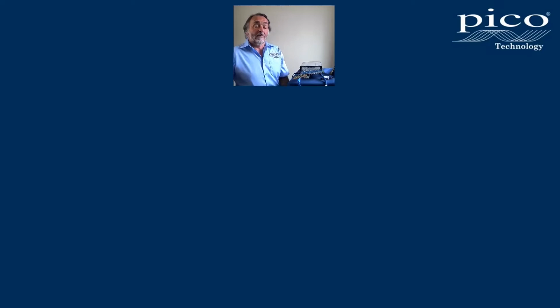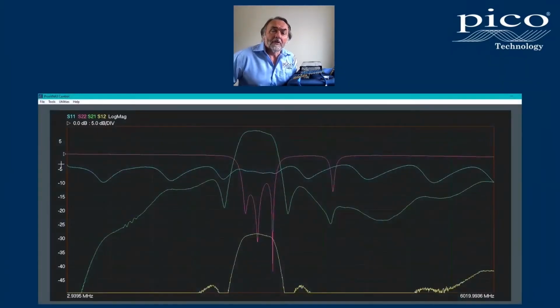Now, instead of 4 S parameters in 4 display channels, we might choose to view all 4 S parameters on a single plot. Each display channel can now support up to 4 live traces, as seen here. An obvious benefit being that the display alignment between each of the 4 S parameters for our device under test is now much more clear.